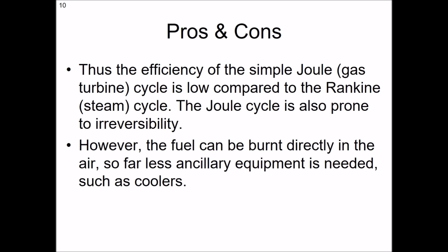It is the same for a reciprocating engine: what we want the piston to do is expand really slowly, but we know we're not going to get a lot of speed or a lot of RPMs out of that. So almost in a very analogous way in the Brayton cycle, we're going to have a lot of irreversibilities, because what we'd like to do is throw hot air out the back of the engine as fast as possible. In reality that works very well, but on a theoretical basis, we wouldn't want to do that.